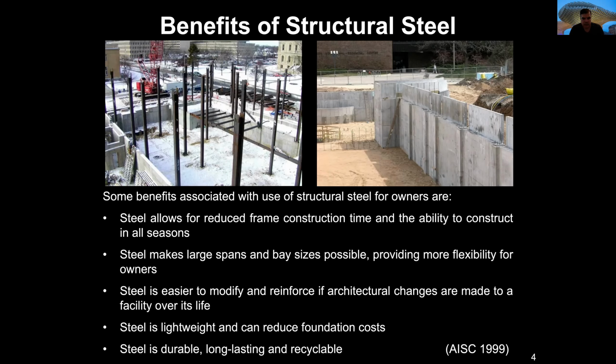It also provides more flexibility to the owners. Steel is also easy to modify and to reinforce, different to other materials where that is not possible. It's lightweight, therefore the price of the foundations is smaller in comparison with other materials that are heavier. It's also durable, long-lasting, and it's possible to recycle it 100%.